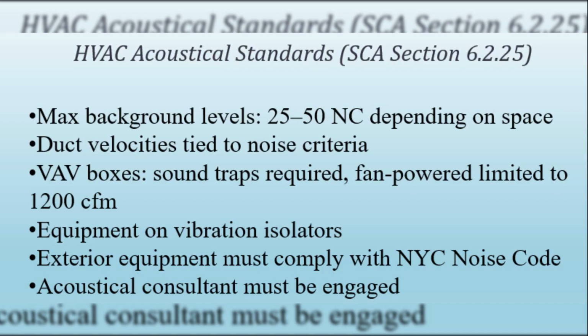If fiberglass lining is used, it must comply with ASTM standards for fire resistance and fungal resistance. It must be fully sealed to prevent fibers from entering the airstream. Diffuser design is also regulated. Standard ceiling diffusers are preferred, while linear diffusers are only allowed when the heating load exceeds 250 BTUH per linear foot. This ensures that design choices are not made for appearance at the cost of noise performance.